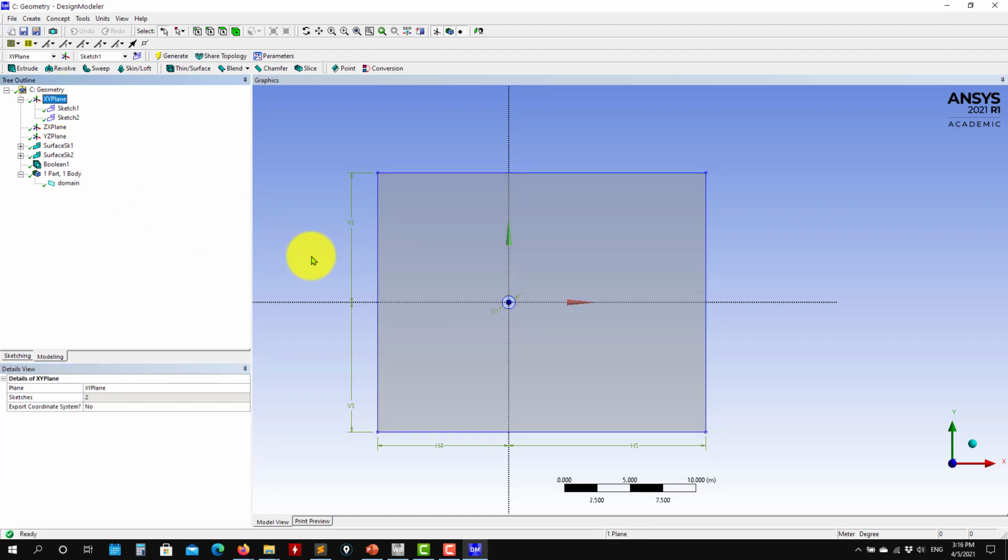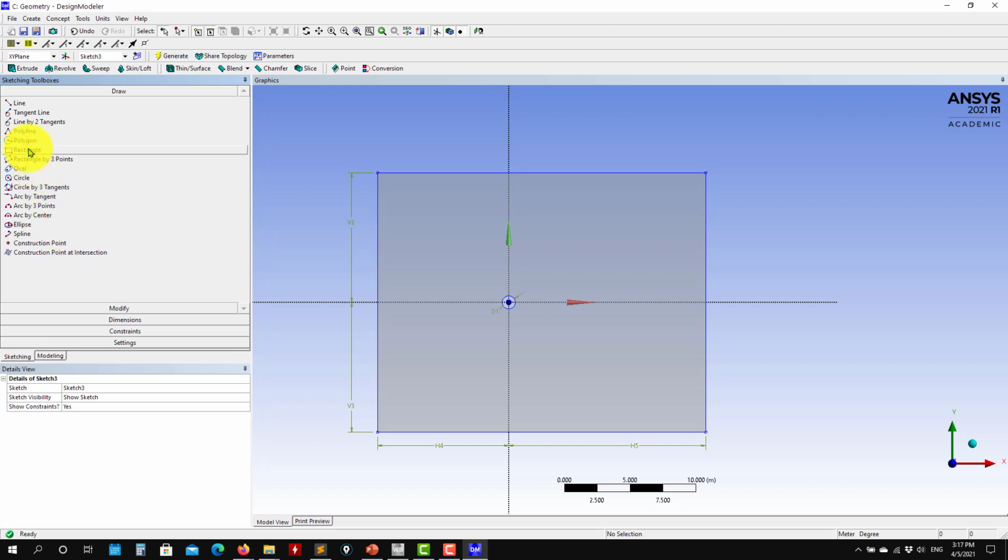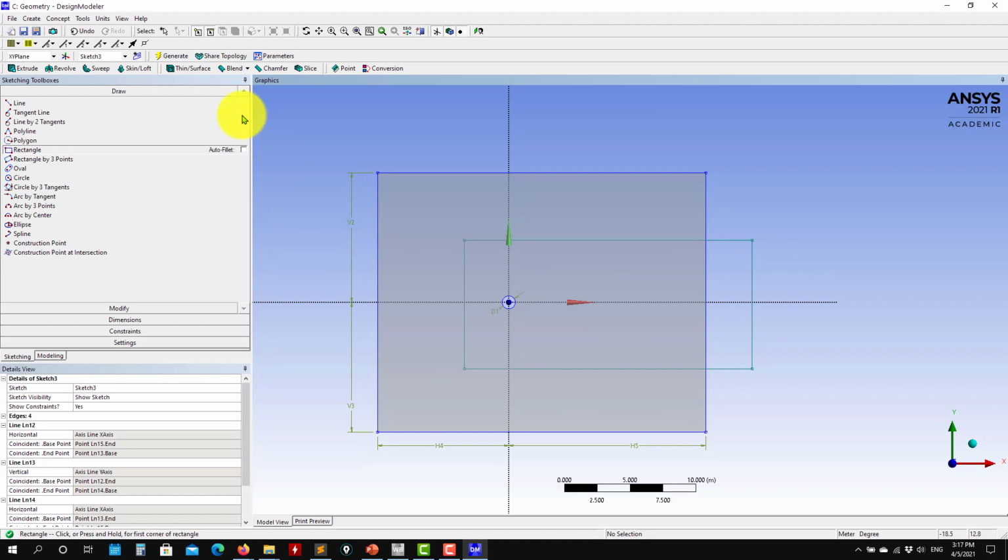Okay, it will be another plane in the same one. It can be a plane, solid, whatever, even a point you can create. Okay. And this is what I'm going to do. So inside this box, I'm going to put more cells. Okay, so when we move to the meshing stage, we're going to see that that option is available. Okay, so let's give some dimensions to this as well.